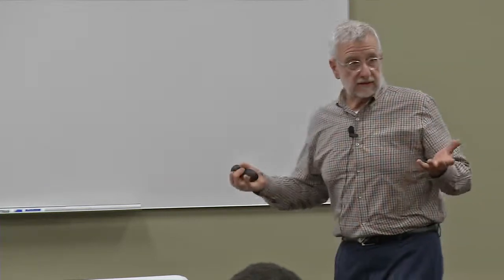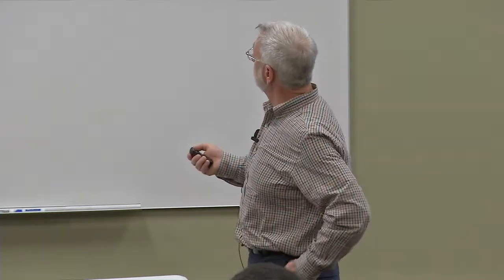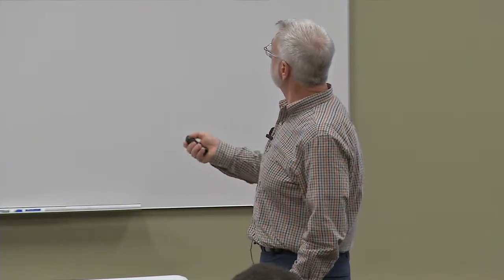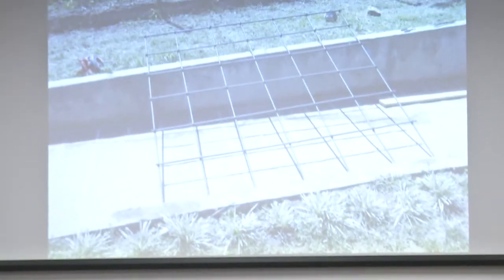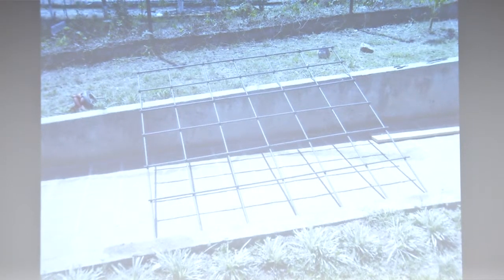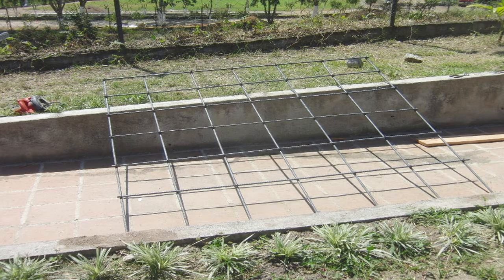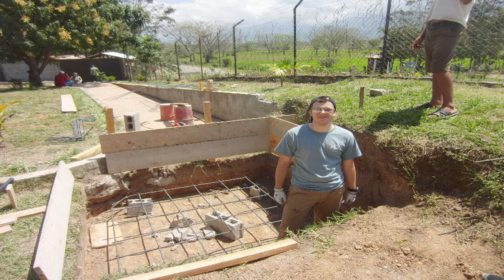Okay, so in this particular case, it's just going to be a cage that looks like this. This is actually on the elementary school side, and so this is the smaller of the two cages here, and we call them cages because that's what they look like. But the rebar is cut and then wire tied together right like that to form the grid. You've got the bars going in both directions, and so this will go in the bottom of the foundation, and it's minimal steel necessary there to prevent cracking in the foundation. Okay, and it goes in right like this.